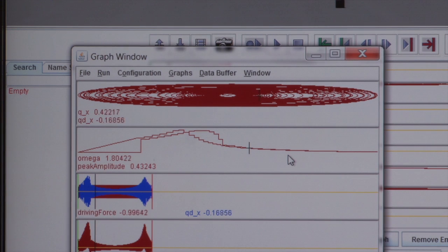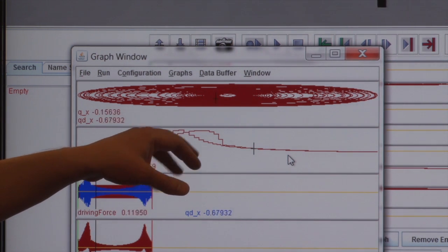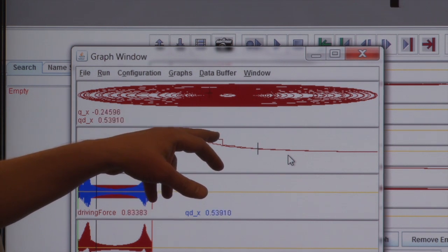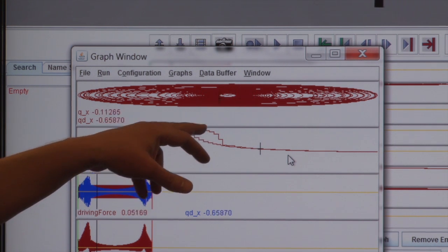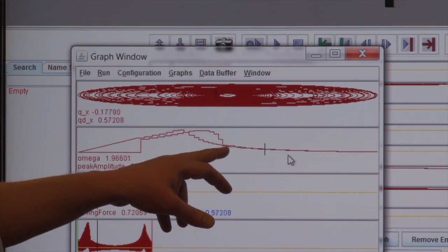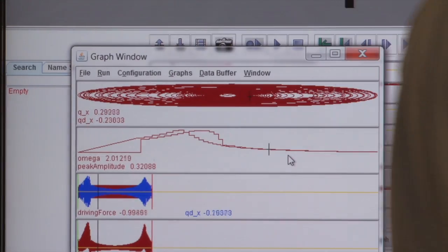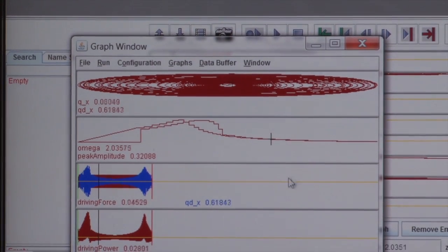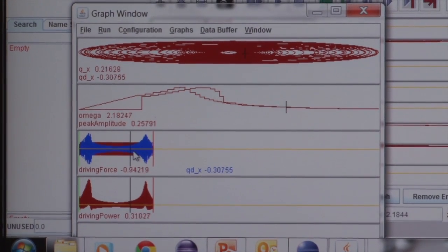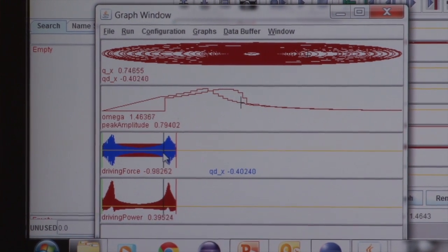Okay, the point I want to make is that driving these things with a sinusoidal input as a function of time is tricky to stay at resonance, because if you go a little bit above the resonant frequency, you drop off. So you have to stay a little bit below it if you drive it. Basically, you want whatever driving force you're using to look at what it's currently doing and adjust based on that. Here it is coming back up the curve.